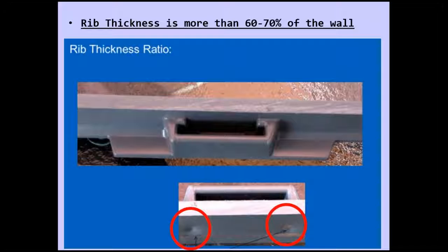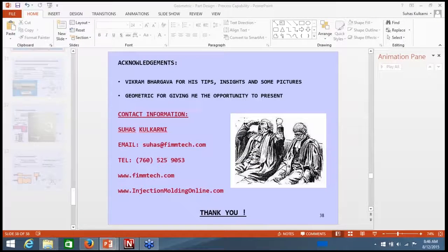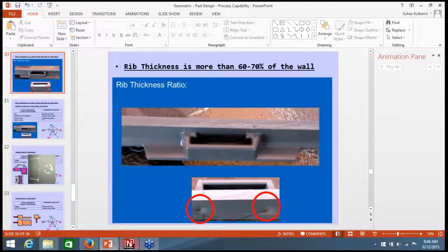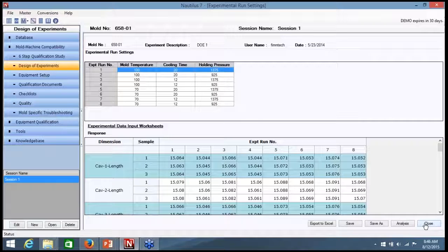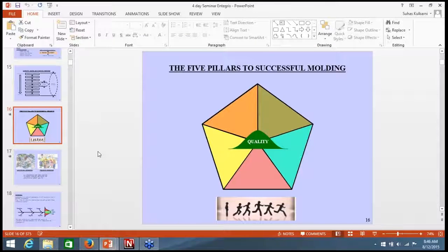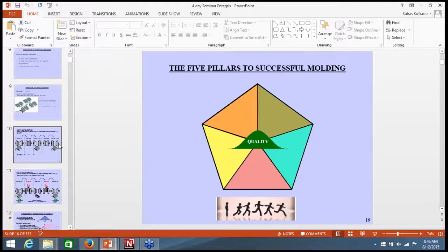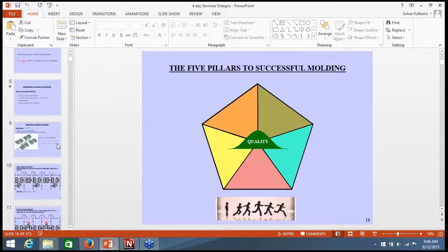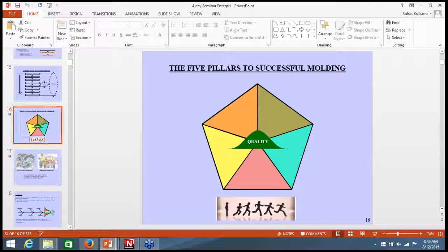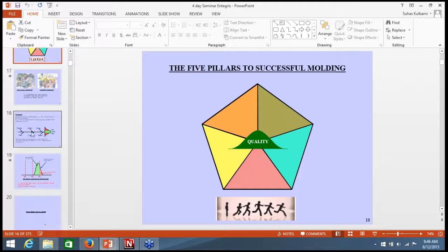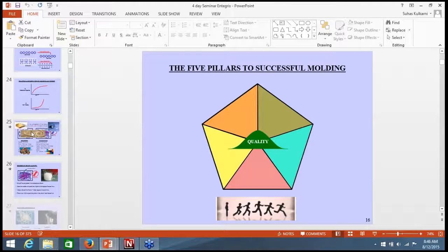Okay, the next question is, why is it called a cosmetic process window? I think in your presentation you had one term. Yeah, I call it a little bit differently. I'll bring up my software here actually. Even before that, let me see, how do I present this? If you can't mold parts cosmetically, you can't mold parts dimensionally correct. QC is not going to look at the parts if they've got flash on them or short shots, right?